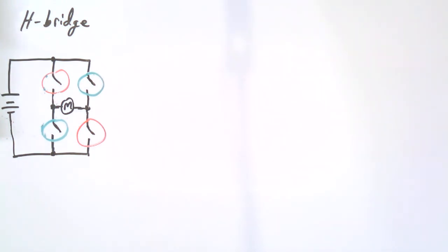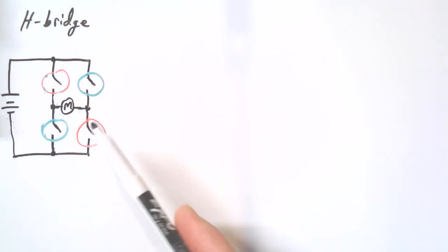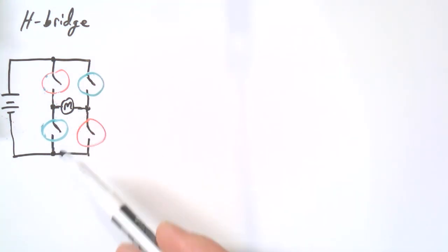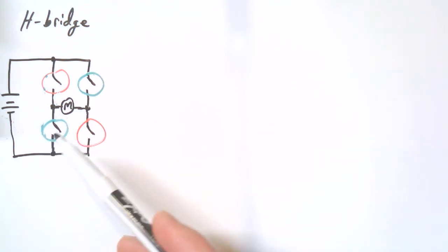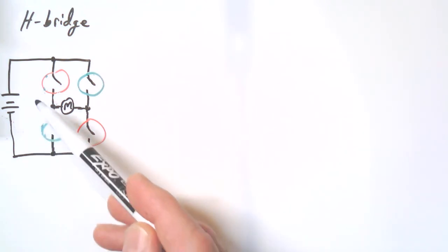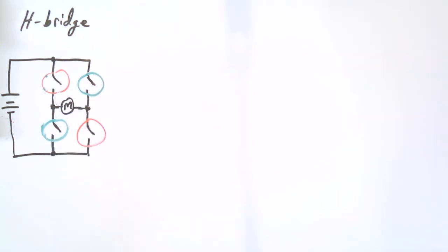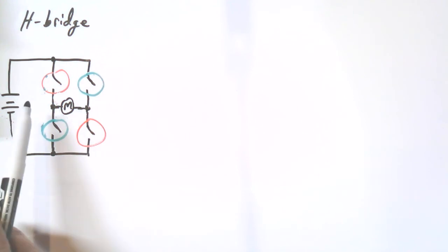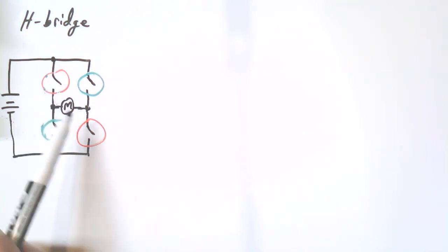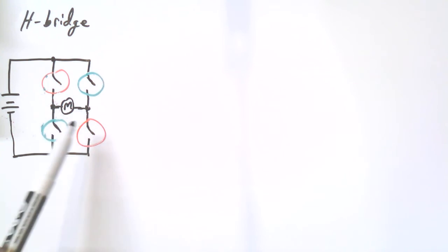One of the simple first exercises that we'll do in lab is to just implement this with an industrial switch. And the easiest way is probably just to take 4 normally open contacts and attach them to an actuator. One thing I might mention, I say we need 4 normally open contacts. You can see that they are color-coded green, so don't let that confuse you. The drawing I did was just to differentiate between the sets of contacts.